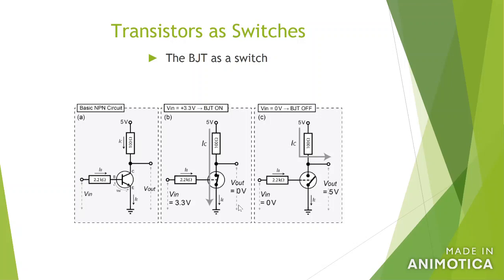So you can see this is another beauty property for transistor. We can use a transistor to work as a switch. It's not a real switch, but it is equivalent to a switch, right? And the switch can be controlled by applying different voltage on this side. If we apply 3.3, then it becomes a closed switch. And if we apply 0 volt on this side, then it's an open circuit. So that's another very important property for transistors.